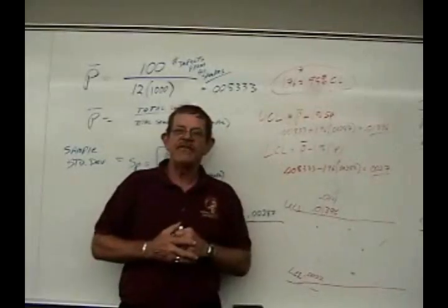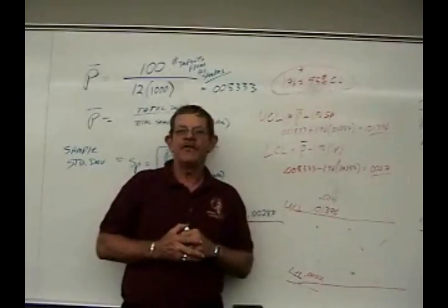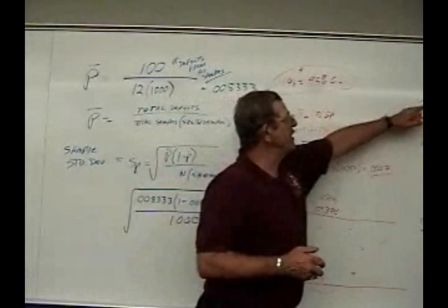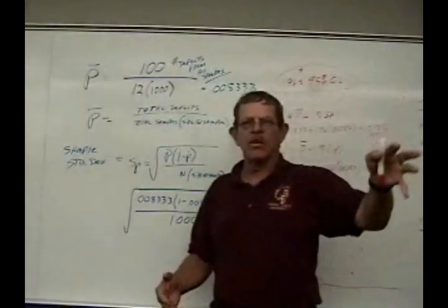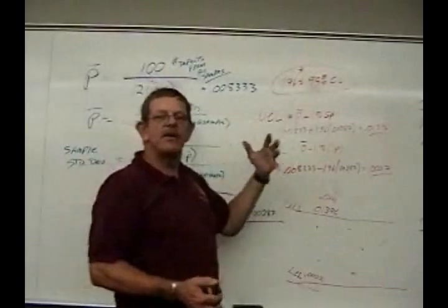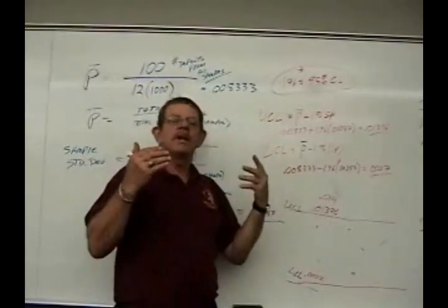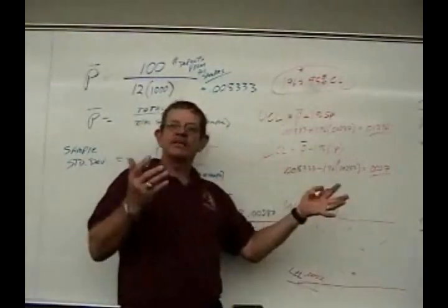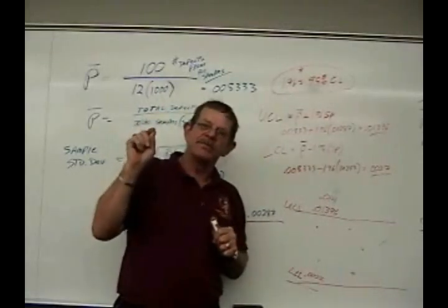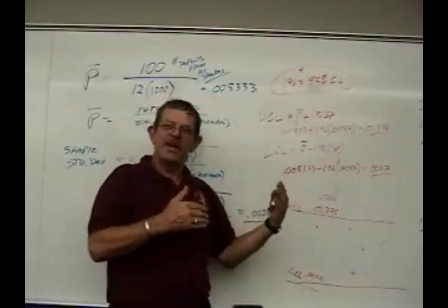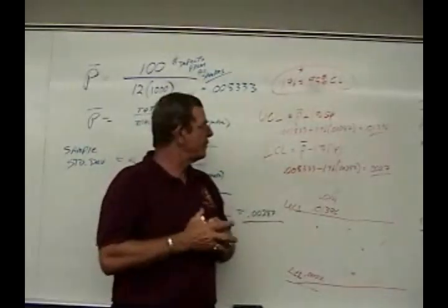You can measure the defects in parts that you manufacture, typically in a size of 1,000. We could say we had 7 defects, 9 defects, and so on out of 1,000, and you would have a P chart. That gives you an understanding of how your process is in control without actually dealing with the measurement size. You're looking at defects or errors, okay?